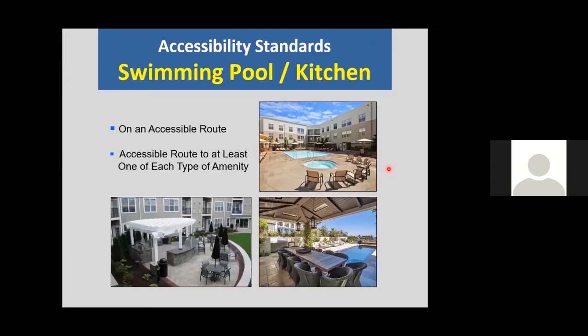Recreational facilities are required to be located on an accessible route per HUD's guidelines. Now with newer IBCs and ANSI standards, we could be looking at, for state project requirements, a higher level of accessibility in these recreational facilities. So far, there's a similar exemption for what we call type B dwelling units in the ANSI standard.